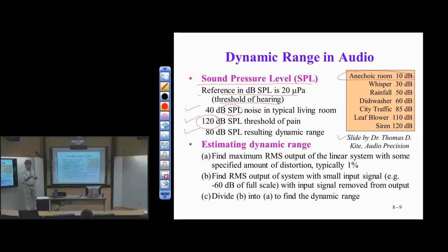And the stereo system has its own effects that you can pick to enhance the playback. You can mimic a concert hall, which is a convolution effect of the impulse response of a concert hall. And you obtain that impulse response by a pseudo-noise sequence, sent over speakers and picked up by microphones in the hall you're trying to mimic. So another pseudo-noise application.